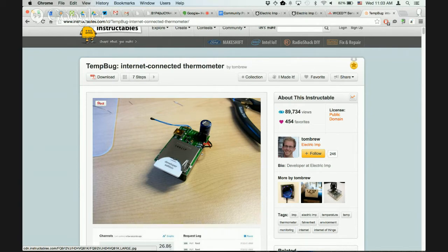So iBeacons are a little different because iBeacons aren't two-way communication. They're kind of like Bluetooth that's been cut off at the knees because they have only one very simple purpose, and that's just to advertise. In a lot of Bluetooth devices, like say the Wicked Sense Kit, there are 2 phases of communication. There's the advertising phase where, hey, I'm here, I'm a Wicked Sense Kit. You can connect if you want.